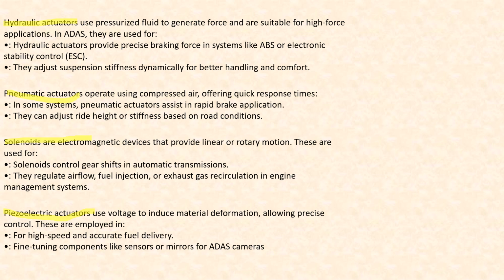Okay, especially solenoids are used to control gear shifts in automatic transmissions. Especially in automatic transmission, the solenoids are extensively used. And next is piezoelectric, where it is used for extreme high speed and accurate fuel delivery. For example, again I will go back to the example of automatic emergency braking.